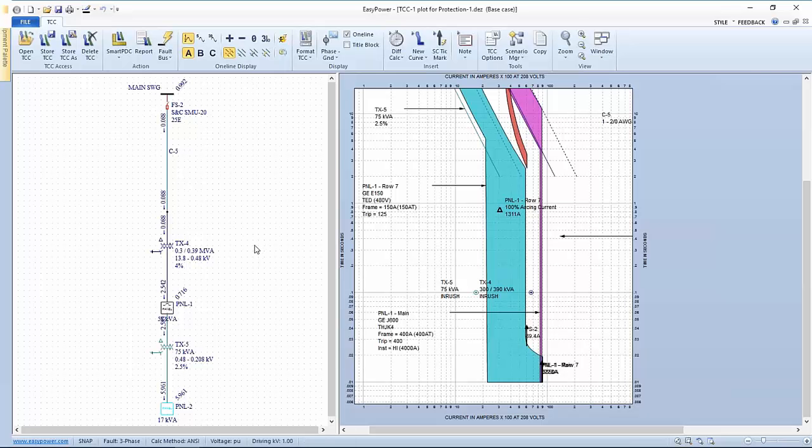Now there's a couple other things perplexing about this. For starters, this particular fuse is in the 480 volt section, 480 volt part of my system, and my load that's actually faulting is in 240. And when we look at this, if we look at the incident energy, we can see this is very high incident energy.